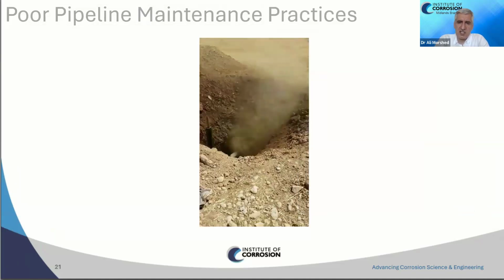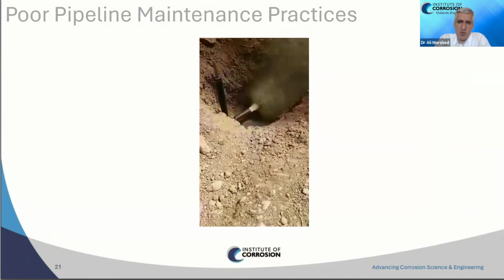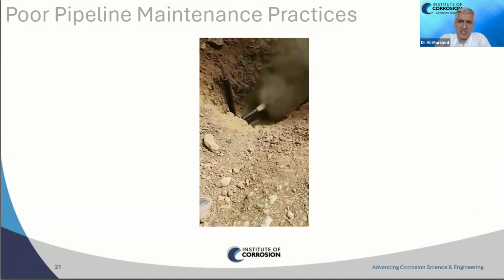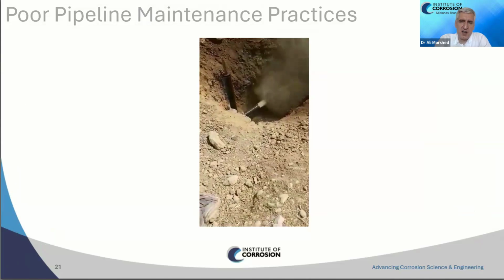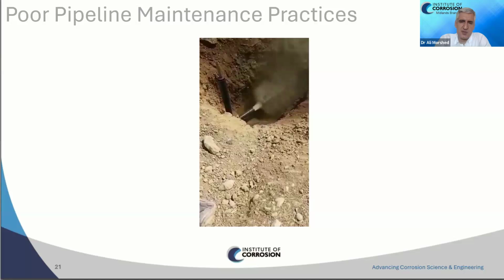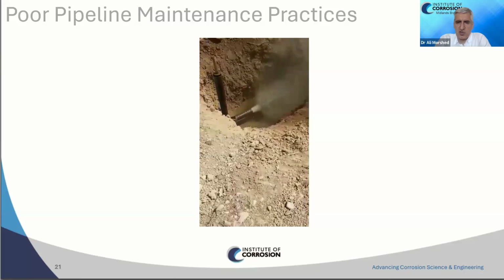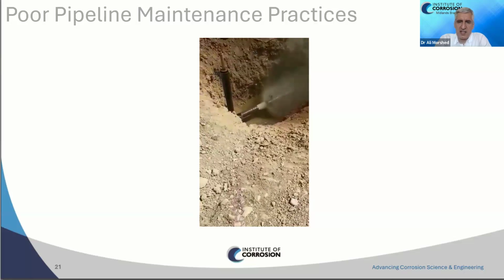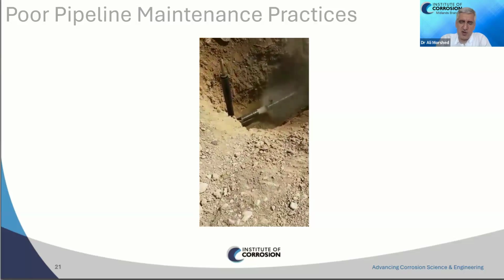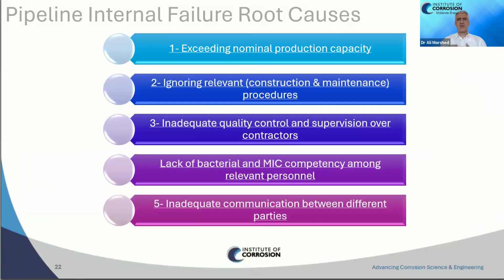Here is another case. Unfortunately, we had another failure when the system was opened up. A pit was excavated, and as you can see here, we have a gas pipeline, and both gas and water are coming out of this break introduced into the system. Again, the good news here is, as you can judge by the color of the water, that no corrosion or very little corrosion had taken place.